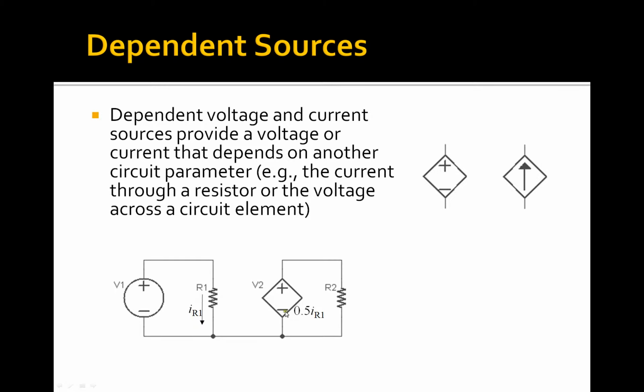Over on the right-hand side, we have another voltage supply, but this one is a dependent voltage source. It provides a voltage that is proportional to the current delivered through resistor 1. In all the circuit schematics that use this abstraction of dependent sources, we will have some indicator beside the source as to what it depends upon and what the relationship of the dependence is.